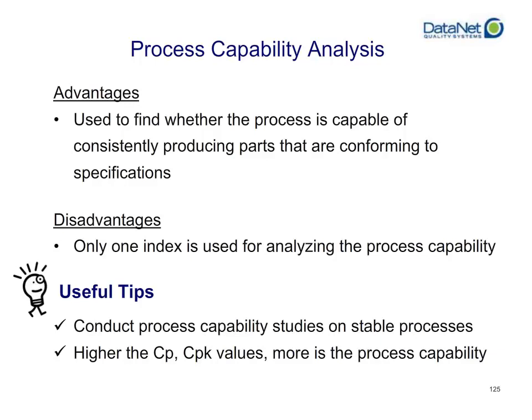You need to be able to both say, is CP high? If so, is it close to CPK? And then whether or not it is, you want to be looking at the control charts and the histograms to see where that actually falls. You also want to be able to compare the way it is now versus how it has been in the past to see if you're improving or getting worse. You can only run these capability parameters, the CP and CPK, if your process is statistically stable, meaning your process is currently in control and has been fairly in control for the data set you're running the capability analysis on.